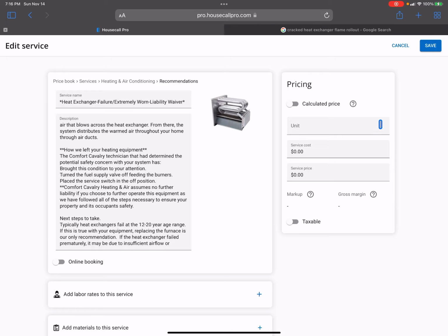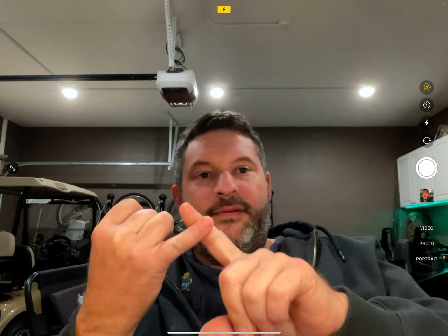at this moment, but like I said, it may not be a safety concern. You may not have high CO in the supply. You may not have high CO in the flue pipe. You may not see a visual crack. You may not see holes or stuff like that in the heat exchanger. But there's still a potential. You may have really bad impingement today, and it could crack literally overnight. I mean, you don't know when it's going to crack. So I still leave it off, and I'm not being a pusher. I show them how to turn it on. I'm just basically covering myself, and you need to consider that as well, right?